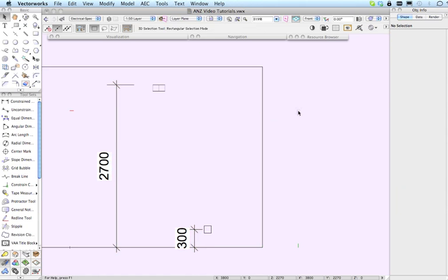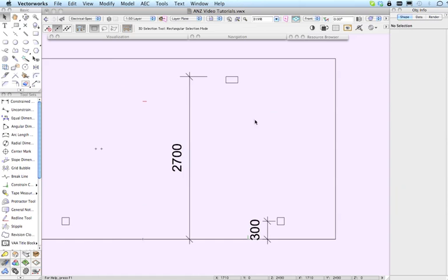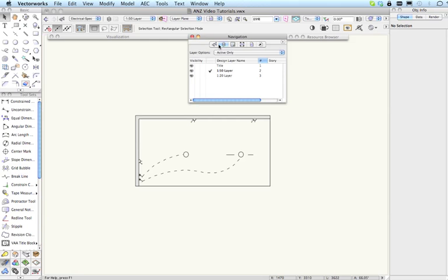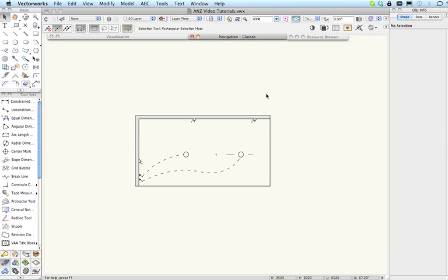So that's why we've given it the ability to have these simplified representations in 3D, so you can actually see these things, particularly if you were, say, in a hidden line render, something like that, so that you're actually able to see these things and dimension them. And of course, if you turn off the class in any of the views, if we go to here and we turn off the electrical spec class and make it non-active, then all of the electrical stuff is going to appear or not appear. So hopefully that's given you a few ideas of how you can go about using these symbols.